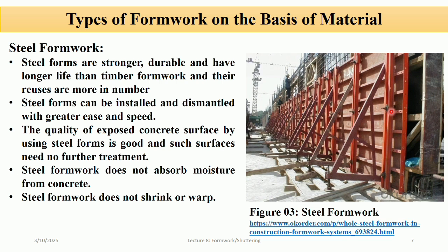And it is easy to clean and maintain the steel formwork, reducing the risk of damage or contamination. It can be used for complex designs. It reduces the labor cost, and steel formwork is environmentally friendly. So steel formwork can be installed and dismantled with greater ease and speed. The quality of exposed concrete surface by using steel formwork is good, and such surface needs no further treatment. And steel formwork does not absorb moisture from concrete, and steel formwork does not shrink.